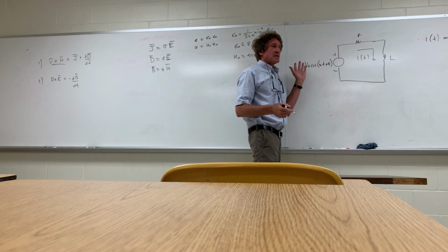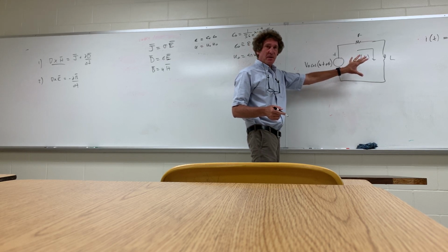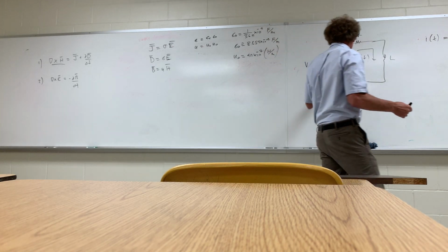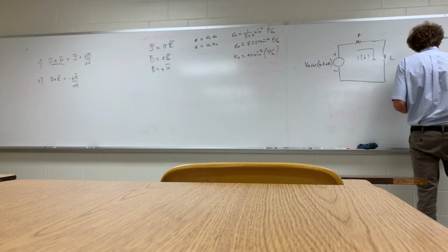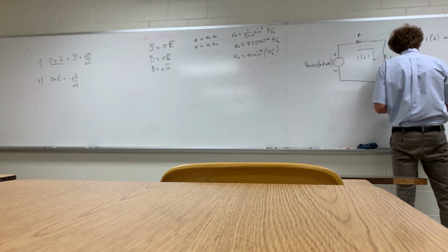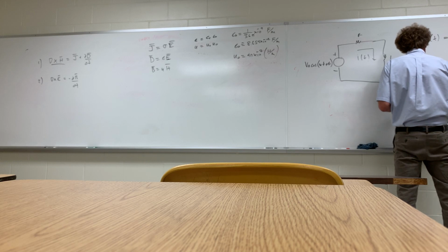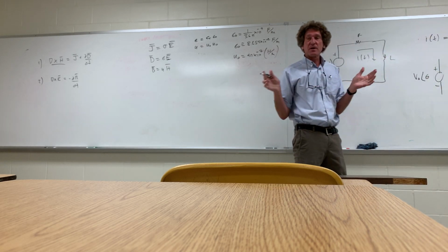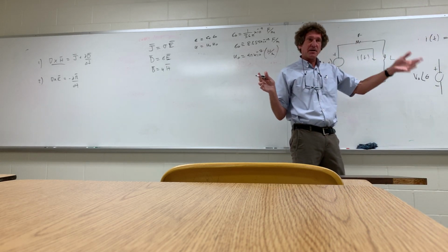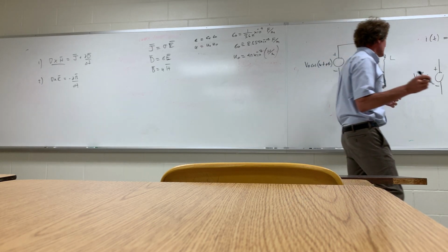What is typically done is you don't solve this in the time domain, do you? You put it to the phasor domain. Do you all remember that? And in the phasor domain, that voltage source becomes what? It becomes plus or minus the value magnitude V naught, and then it's at an angle of whatever that phase angle is. Do you all remember that? Now we've eliminated frequency. Do you all remember? I'm not going to go through how you do it. I mean, we can if you need to. See me in my office after class.